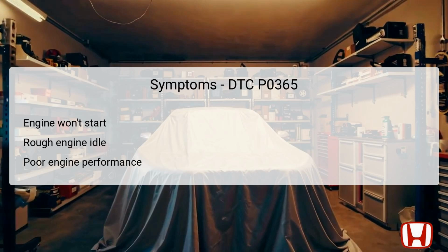This is directly tied to the CMP sensor B's function in determining the timing necessary for fuel injection. If the PCM cannot receive signals from the CMP sensor, it fails to manage fuel delivery appropriately, resulting in a non-start condition. Additionally, if the engine does manage to start, it may exhibit a rough idle, meaning that the engine's